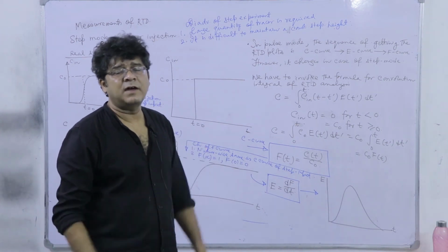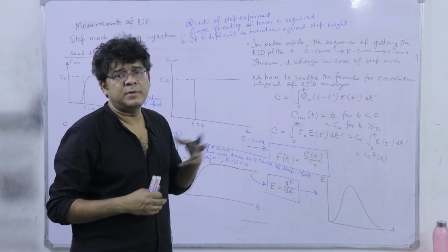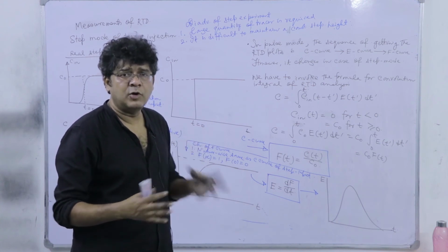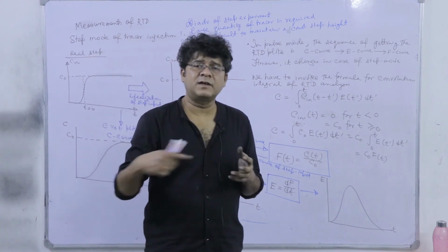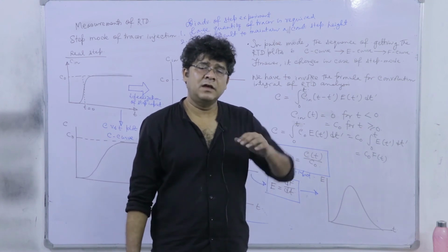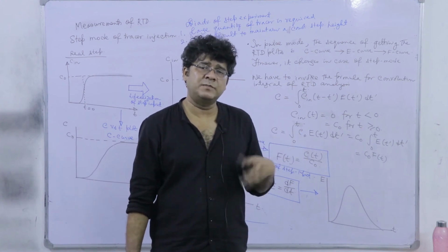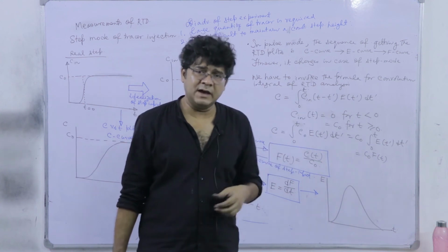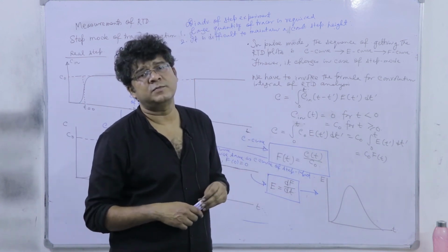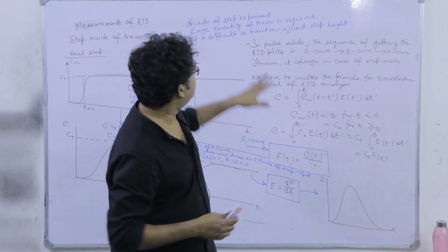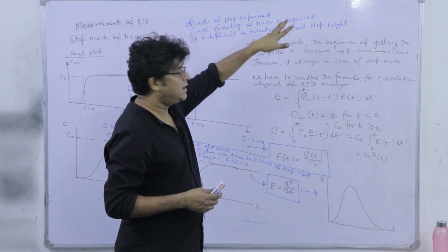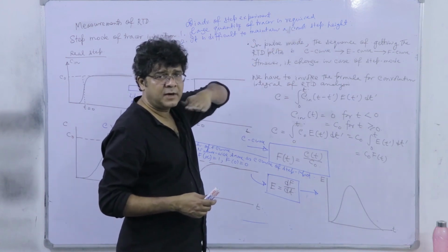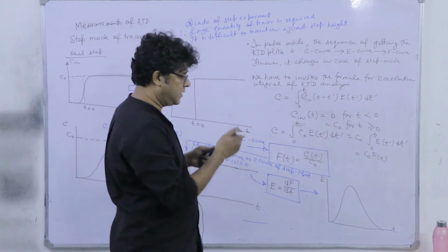And there may be malfunctioning in the pump, the pump voltage in the motor coil may have certain fluctuations, and because of that the pump rotational speed will change, and the delivery rate, as it is proportional to the rotational speed, will change. So there may be a problem in maintaining the constant step height throughout the entire duration of the experiment.